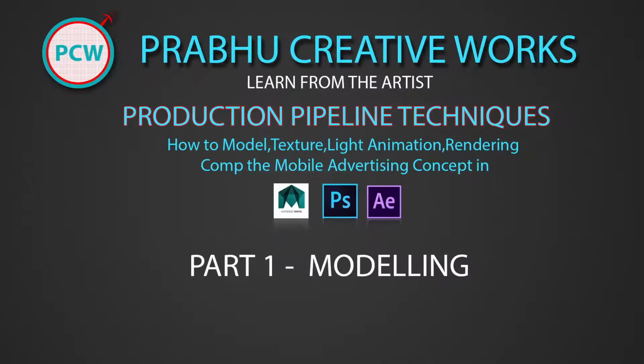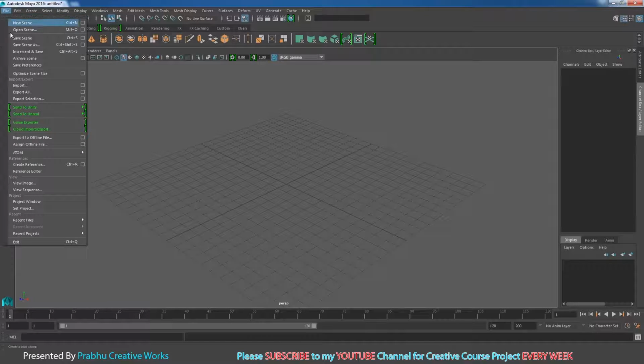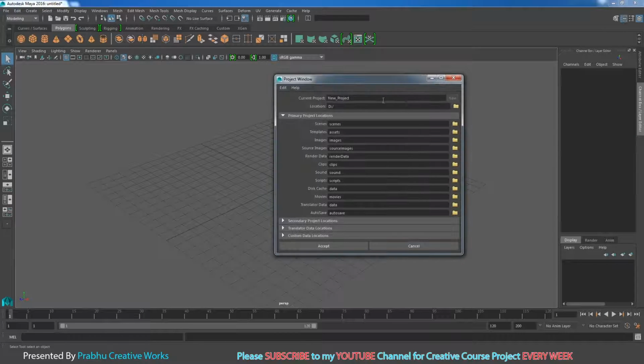It is a complete course project. Please learn them in order. This is part 1, modeling. Okay, before we get started, you need to set the project folder. It's really important. So go to File and choose Project window and choose New Project.